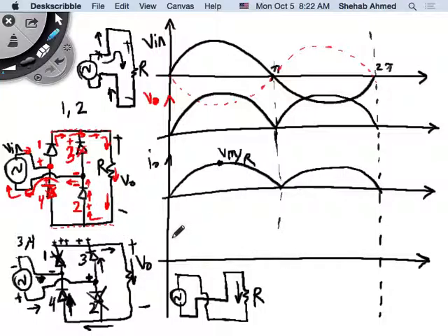How about the voltage across diode 1 and 2? Yeah. So diode 1 and 2 initially 0. And then, depending on the polarity, let me draw it nice. So this is diode 1, for example. Will it not go up, like right there, to switch it high? So here, initially they're on, so the voltage is 0. And then they're off. When they're off, what do they see?